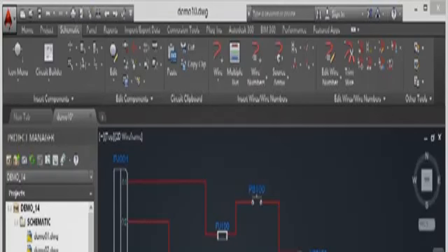What I've got in front of you, again in the Demo 14 project, in the Demo 10 drawing, is a point-to-point wiring diagram. And I've got that coming off of one of our connectors in our drawing Demo 10. So you can see there's PJ001, our connector, and all the wires coming off of the pins are going along with components within the wires joining to our conveyor motor. So that is a point-to-point wiring diagram, because it's going from one point all the way across with components in the wires to another point.